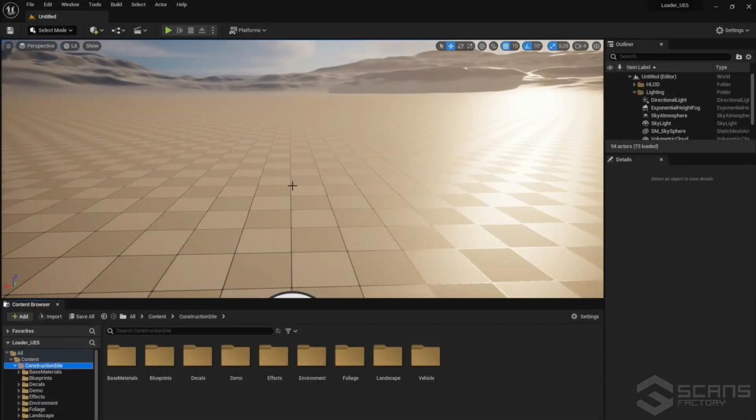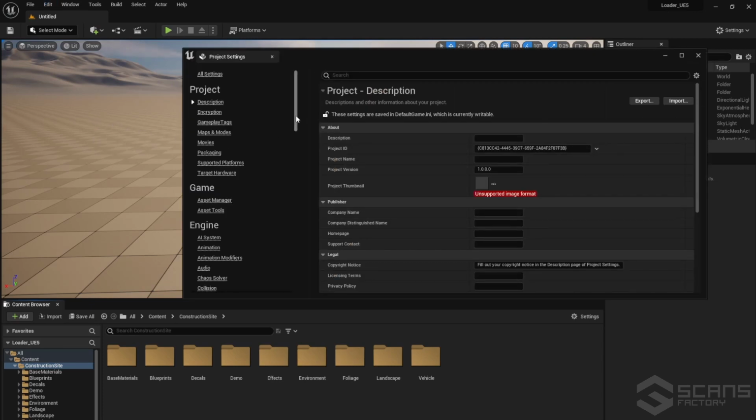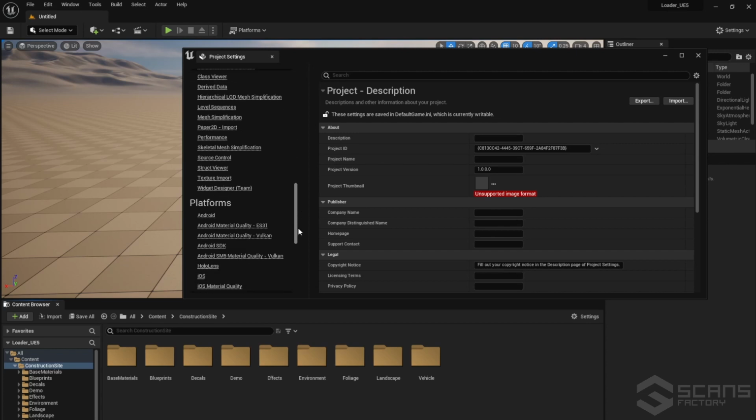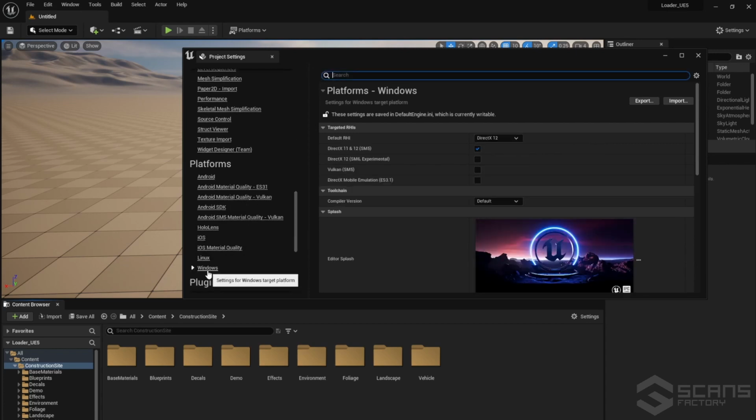I will load the deformable terrain, but Unreal Engine 5 has no tessellation option, but we can use Virtual Heightfield Mesh to do that. Please follow the steps. Make sure you have DirectX 12 set as default in your project settings. Go to Project Settings, Windows tab. New projects created in Unreal Engine 5 use DirectX 12 by default.